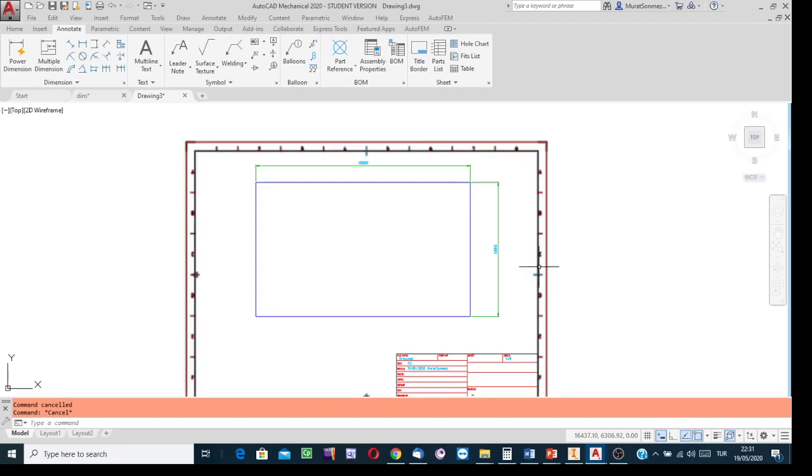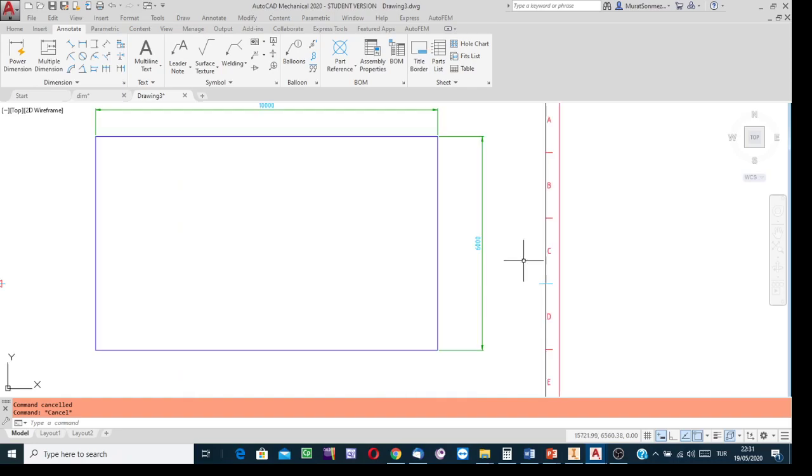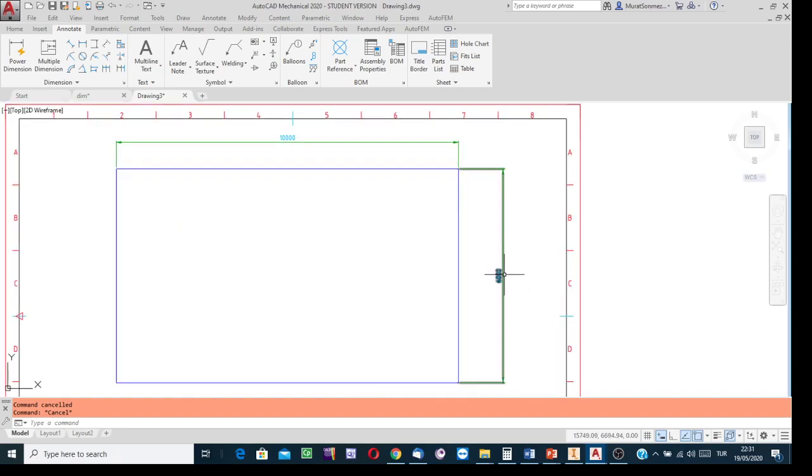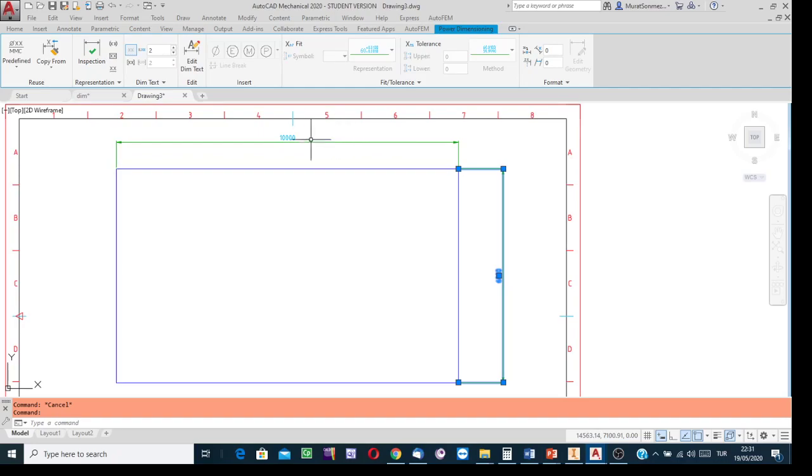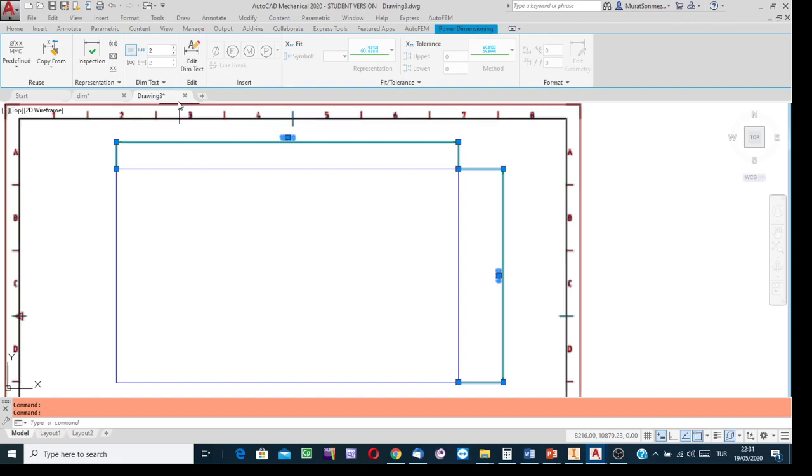Show the dimensions in millimeter. In my method, this is how you can change the unit from millimeter to centimeter. Indicate the already shown dimensions. Select all of them, clicking, and then you see in this ribbon it is written dimension text. Drop this list, and yes, it is my method. Linear scale factor.